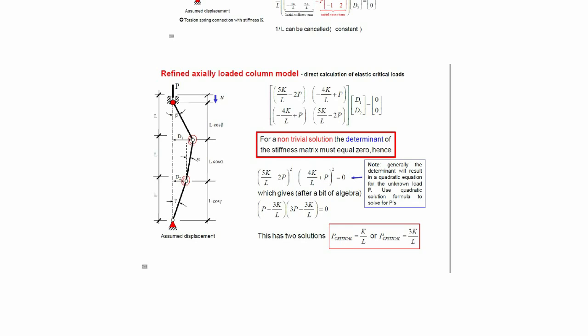Consider all springs and energy due to the loading. Simplify the expression. Make sure there are no algebraic mistakes, otherwise you will get wrong answers. Use the equilibrium conditions to write down the two equations, and rearrange them in matrix form. Two eigenvalues of the coefficient matrix in terms of P are the two buckling loads.